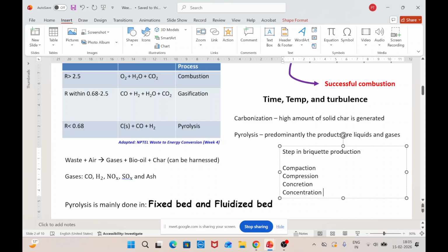So again, the process usually depends upon multiple characteristics of the biomass. Depending upon their flowability, the particle size distribution, and their adhesiveness, the quality of the briquette that you obtain, either from the piston press or the screw press, is going to actually vary.